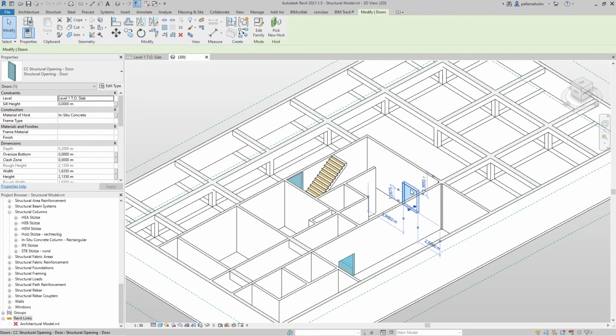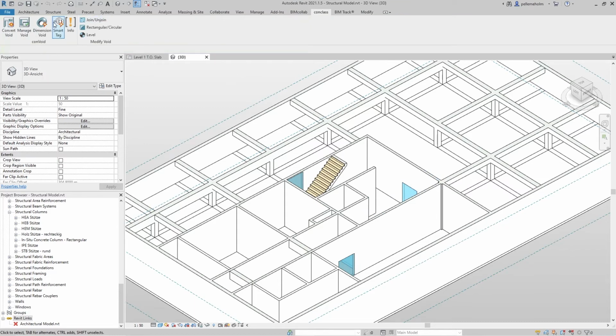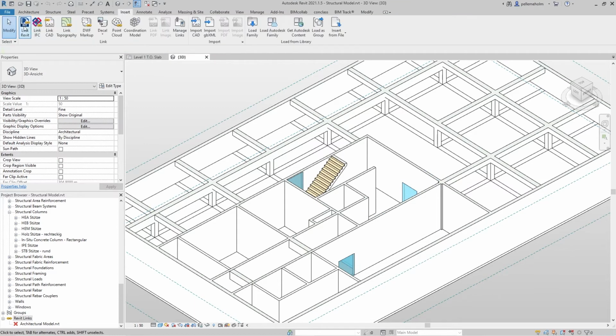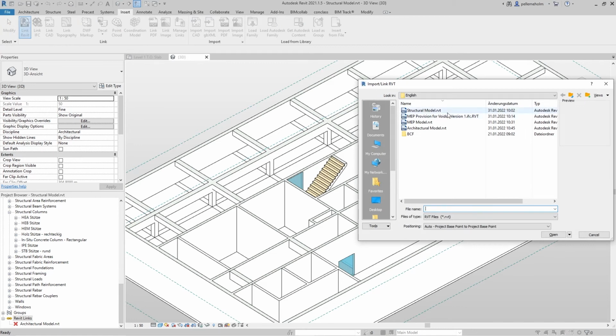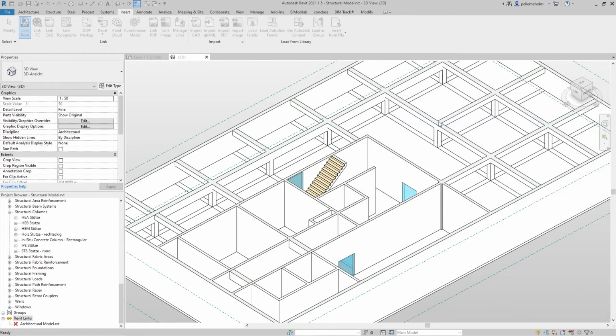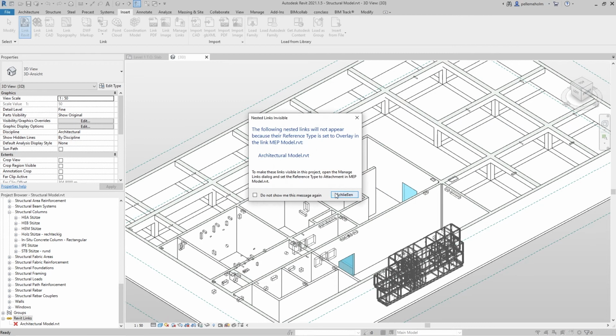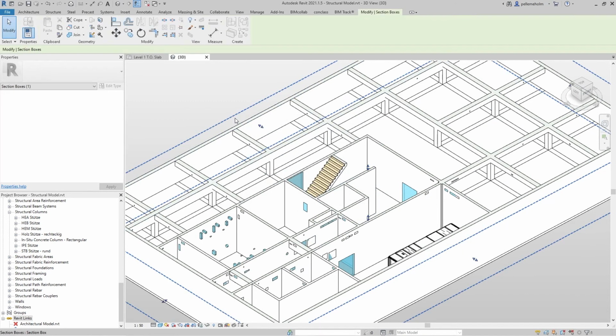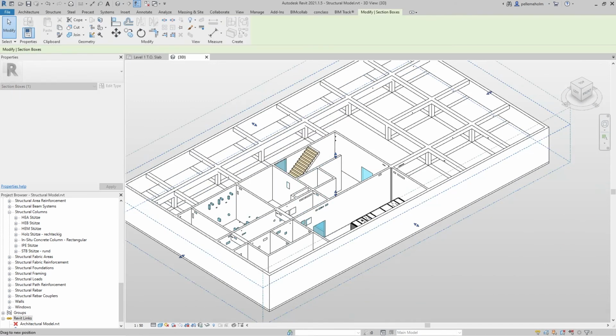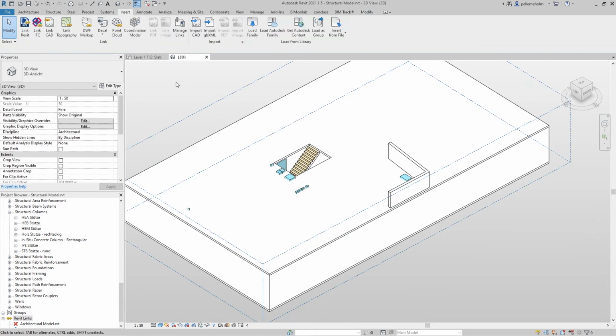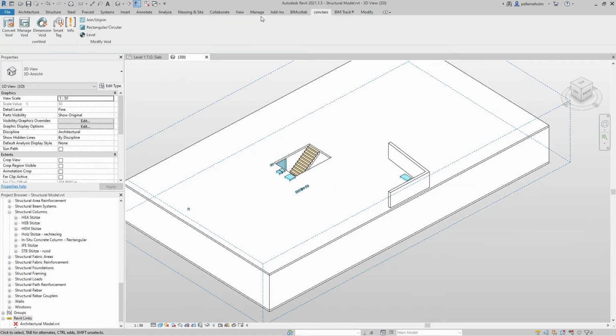As already mentioned, this is also possible with Windows or IFC elements. Before I start the coordination and approval process, I'm just adding the MEP openings to my structural model. On this step, I will also show you how to cut openings with host elements to get real openings, and what ConVoid does to improve the quality of the openings.